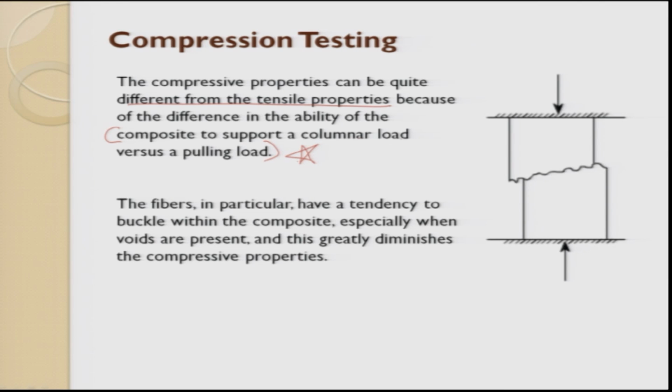In general, composites are very good for tensile load. For compressive load, the reinforcement doesn't take that major load. The fibers in particular have a tendency to buckle, because you keep pressing. The matrix shears within the composite, especially when voids are present, and this greatly diminishes the composite property.